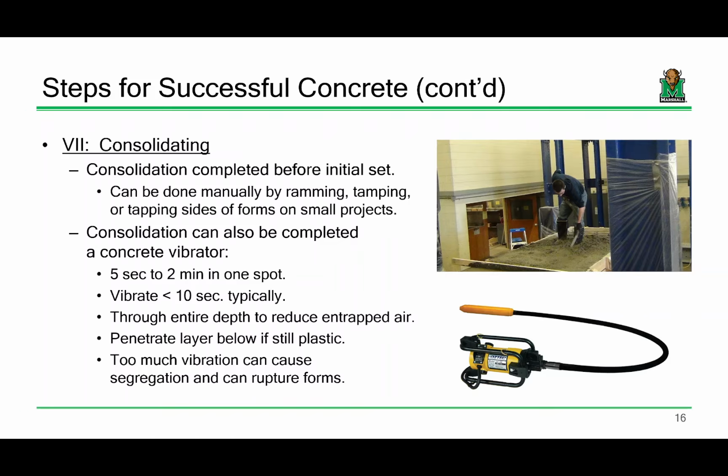Like you couldn't mix it all in one big thing. You had to mix it in batches. But the other thing is it's a very gritty, sort of pasty type mix at the end, right? If you were to use aggressive vibration, what would happen is all the aggregate would settle. You'd have the cement paste and the canoe would crack, right? So using this would be a really bad idea for that type of concrete. Whereas regular concrete that's got gravel, sand, cement, and water in normal proportions, not as big of a deal, okay?